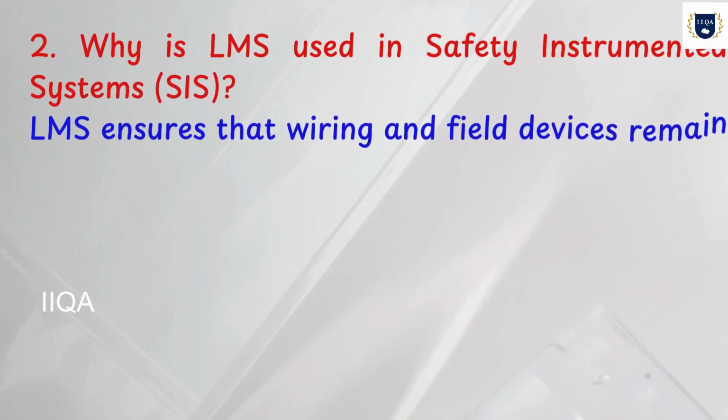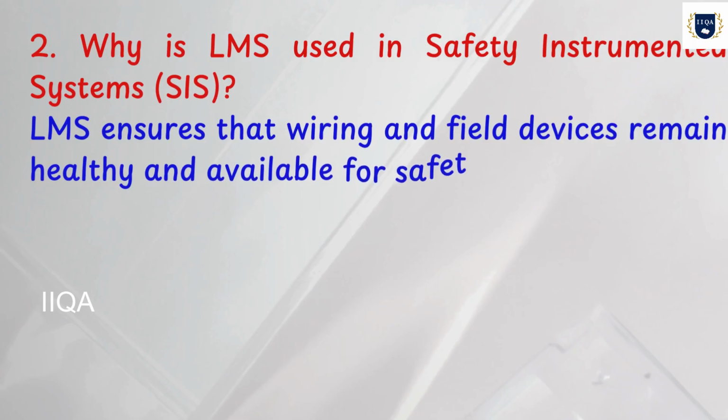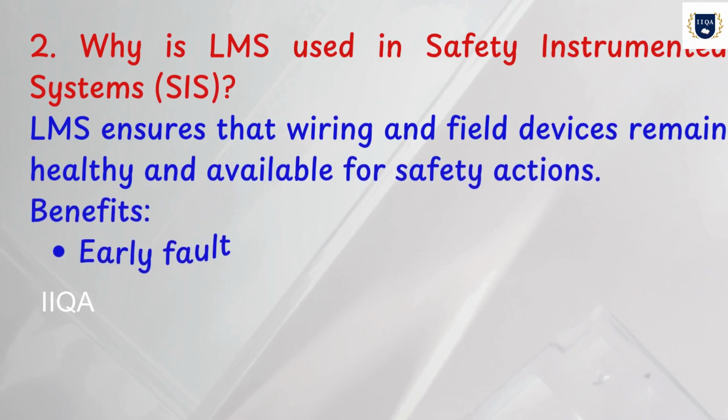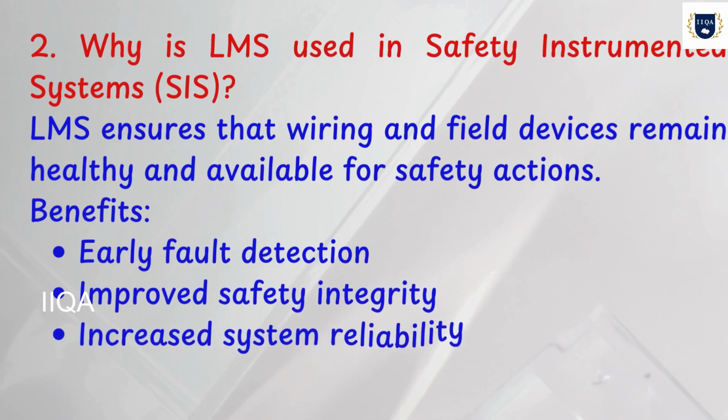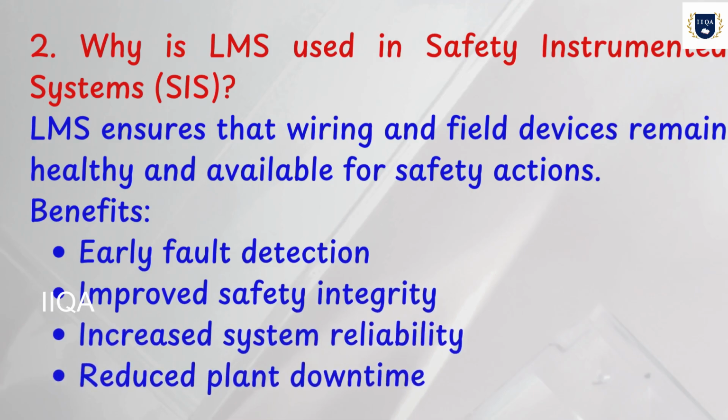Why is LMS used in safety instrumented systems, SIS? LMS ensures that wiring and field devices remain healthy and available for safety actions. Benefits: early fault detection, improved safety integrity, increased system reliability, reduced plant downtime.